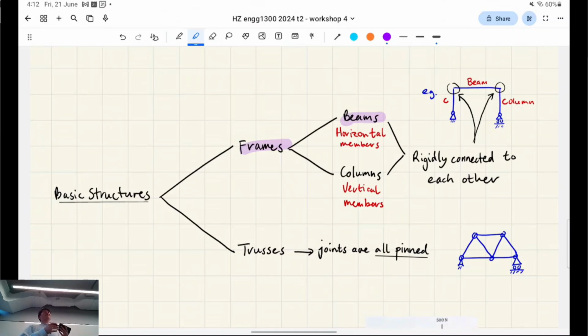I don't want to make promises, but from what I've seen in the midterm, with the shear force and bending moment diagrams, you can graph them in any way that will get you the key values. So generally you can get away with the faster method, which is the graphical method, as long as there's no triangularly distributed loads, which you won't be able to find the key values using the fast method for. And typically Waze is pretty nice. He probably won't give you a triangle or a trapezoidally distributed loads until potentially the finals, right? So this midterm should just be dealing with uniformly distributed loads on beams and point loads on beams, right?